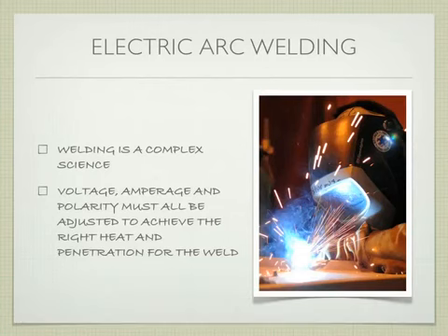Welding. Yes, sir. It's designed that way. The electrode that you're melting is a stronger grade of steel than the steel itself. So when you melt the steel on one side, melt the steel on the other side, plus you have a stronger steel that you're making with the electrode, by the time you make the joint, assuming it's done properly and there are no air gaps or anything like that, the joint itself is actually stronger than the sides, which is the desire.